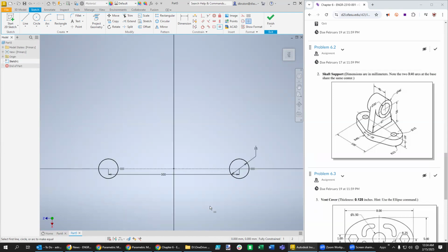All right, now we need this structure that goes all the way around it. And there's a couple of ways to pull this off. I guess we can just rough it out, first of all, with some lines. I guess I see one right here and another one right here. And then another one here and another one here. We're going to have some arcs that have their centers at this point. And then the radius of this outer one is 22.